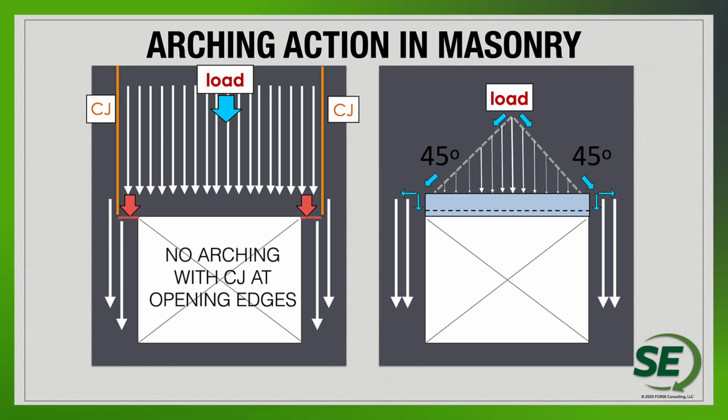And again, we've seen this in even old Roman architecture. We know that this works, especially when we have multiple openings that are stacked. We know that the thrust loads, in fact, don't become much of an issue because they actually cancel out. If you had a series of openings, the end opening would have the thrust force that we'd have to consider, and we'd have to have a little bit more of an abutment there. But again, just recognizing what the thrust loads are and what the implications of that are, once we have that, we know that we have a lintel that can be designed for a lot less force.